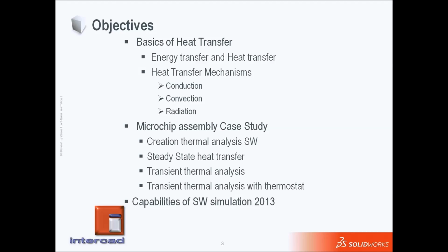Then we will bring this to a real case study of a microchip, where we show you how we create a thermal analysis in SolidWorks. We will have 4 different studies on this assembly. First we consider steady state heat transfer, and then 2 transient thermal analyses, with a single step heat load and a multi-step heat load.